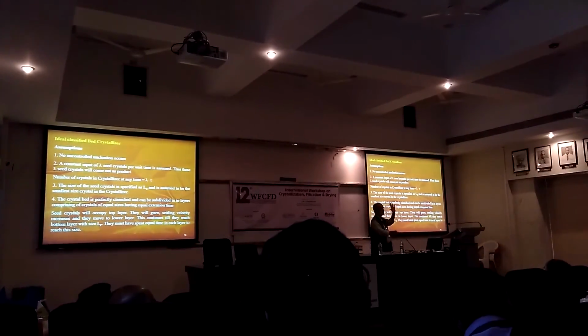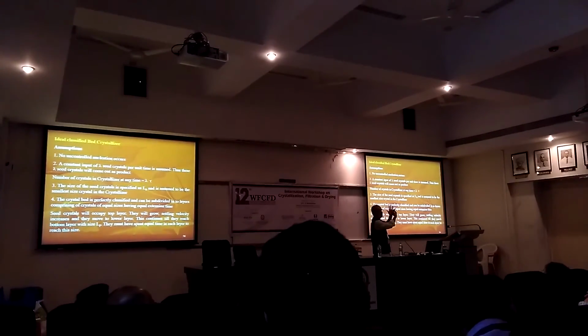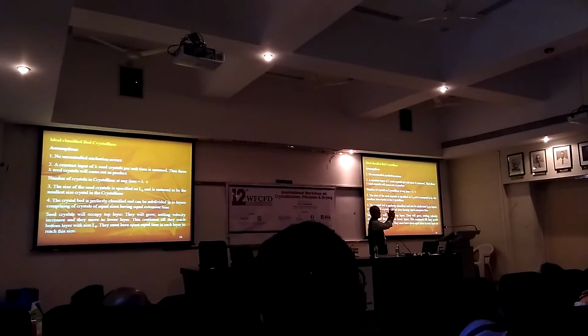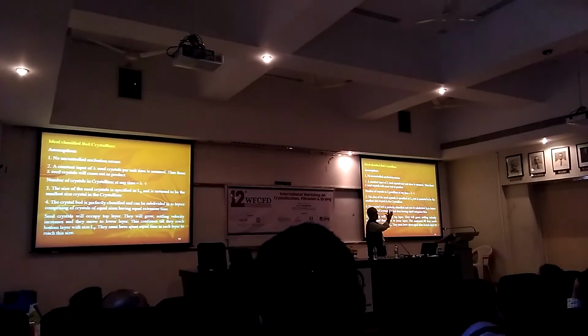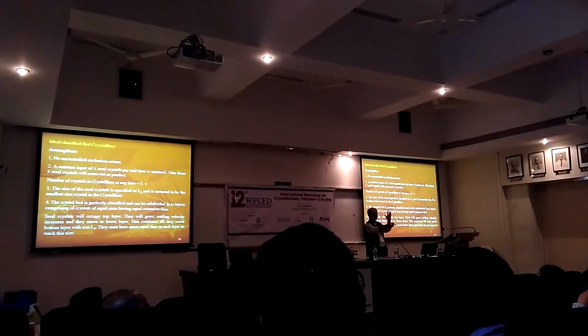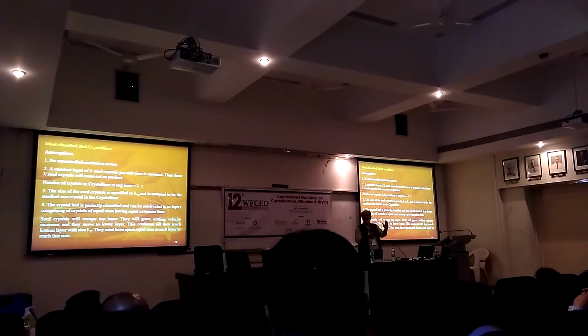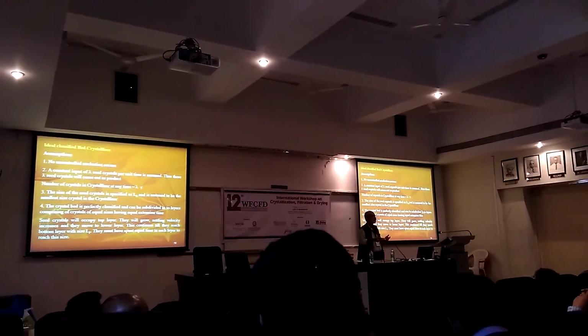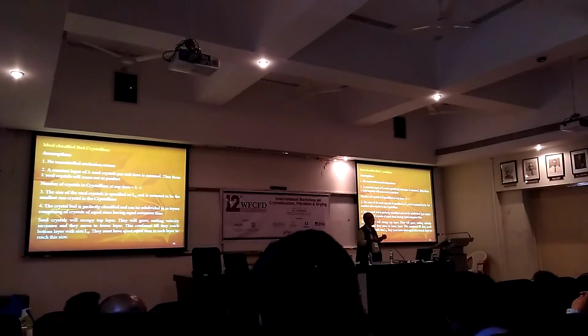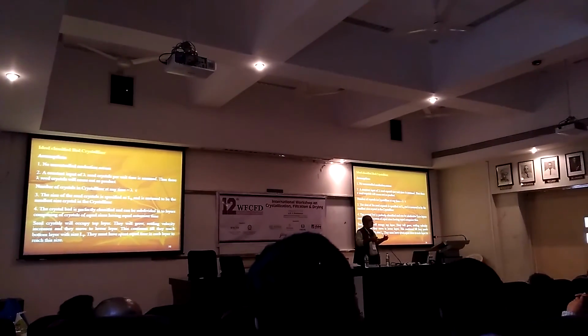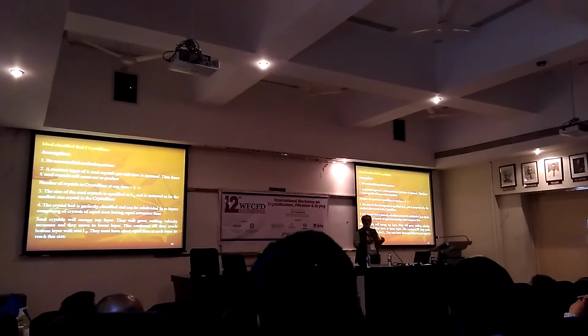If we start with knowledge of the solubility curve, knowledge of nucleation rate, and knowledge of growth rate. Now this is system dependent, and I'm sure Mike is going to talk about how some predictions can be made thermodynamically, which could be a guideline for you to plan experiments rather than doing experiments in the dark or randomly and then hoping for the best.